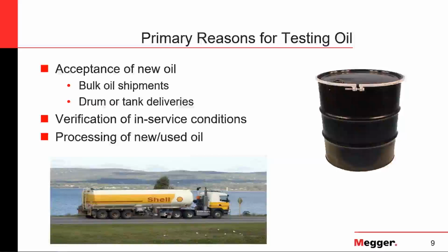Like I said before, a transformer needs to be completely dry to avoid any degradation or early degradation of the insulating system. After the unit has been in service for a certain period of time, for regular maintenance purposes, when we do our maintenance testing, it is very important to include oil tests during those operations.